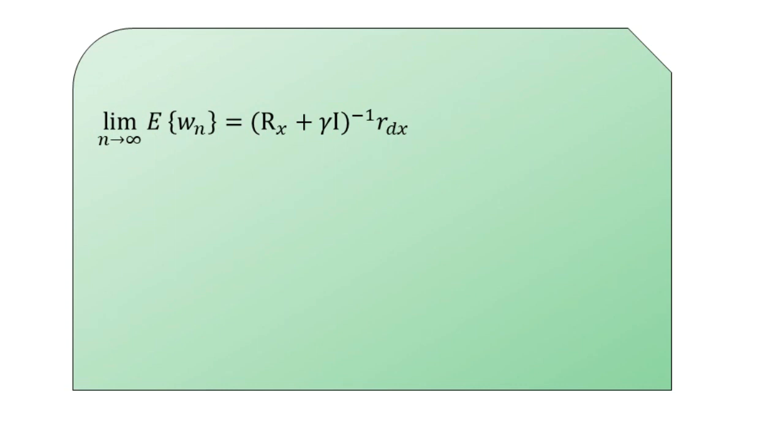Now for minimization of the error, the Leaky LMS algorithm may also be derived by making use of the LMS gradient descent algorithm. So here we have minimization of the error denoted by zeta(n), that is equal to mod square of e(n) added by gamma, the leakage coefficient, multiplied to double mod square of w_n here.